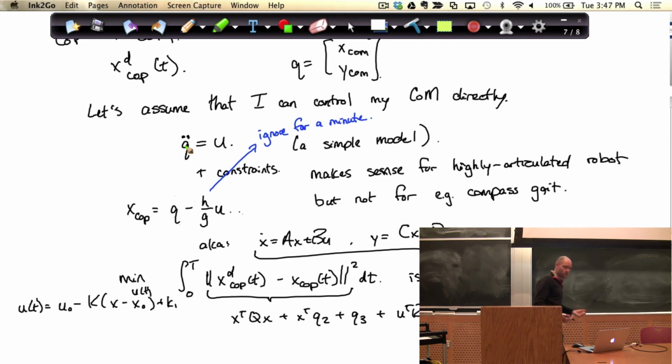So the way we formulate it is as another optimization problem, which we solve for every time step, which says there's some comfortable position for the robot. Okay, this is my nominal position for the robot. Be as close as possible to nominal, subject to the constraints that my center of mass is where I said it's going to be, and my feet are where they're going to be. And that gives me a nonlinear optimization, but one that I can solve quickly with SNOPT.